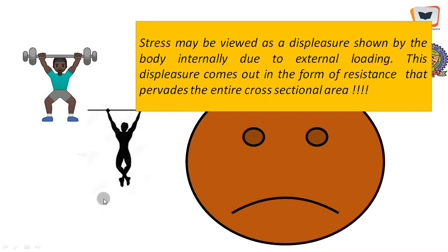The conditions are: 1, the load should be acting centrally on the centroid or over the axis. 2, the section should be taken perpendicularly to the longitudinal axis of a component, and it should be distant away. Then the stress will be uniform.